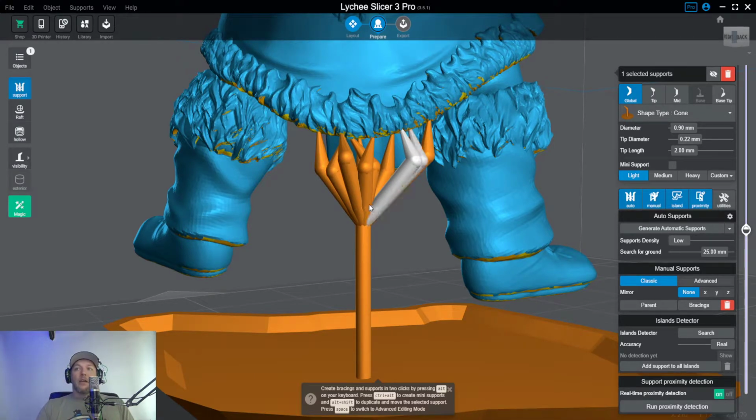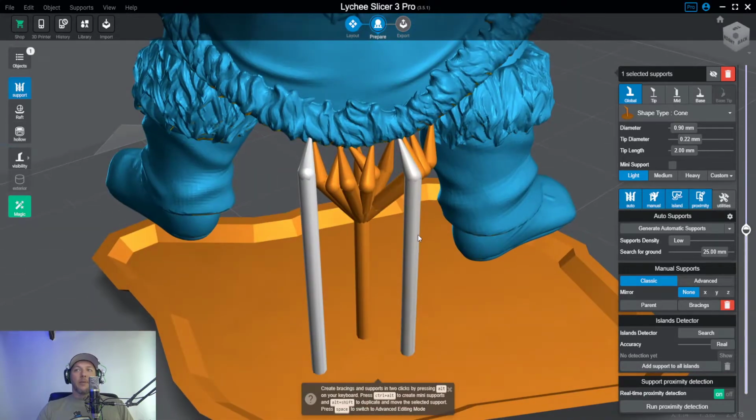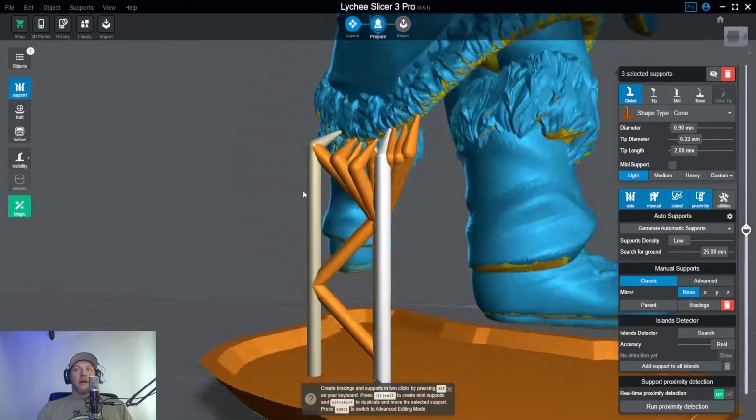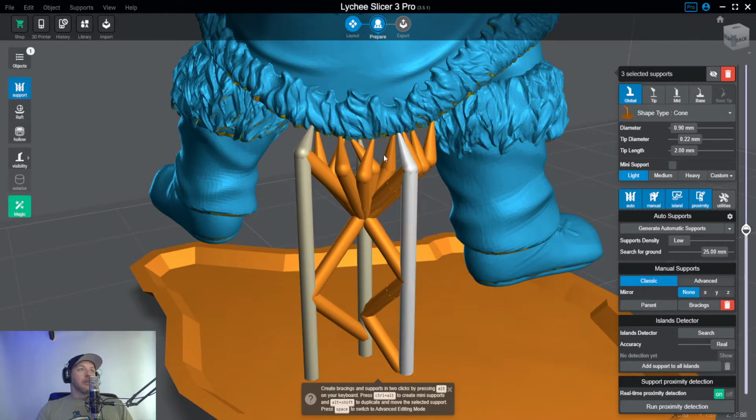unnecessary. Sometimes you'll find that the pillars are necessary. We need to keep that model up, so we need some actual pillars to make bracings with. Like this might be totally necessary. But on that 10 other pillars I made, I was able to reduce the amount of resin usage by making a tree or a fan or whichever method you want to use. But it shouldn't be first on the list.